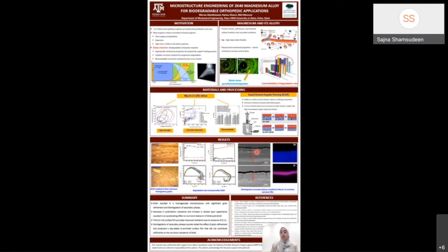surface film. So here we have SEM images of the cross-section areas of both alloys, and we find that in ZK40 heat treated, there was a much thicker and much more coherent film formed than in the ECAPed alloy, where it had a thinner film and the film was starting to disintegrate. We also found by EDS analysis that this film was actually mainly zirconium oxide, and from other research it was found that zirconium oxide was used as coatings on magnesium alloys to improve their resistance.